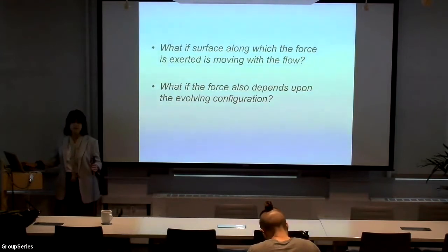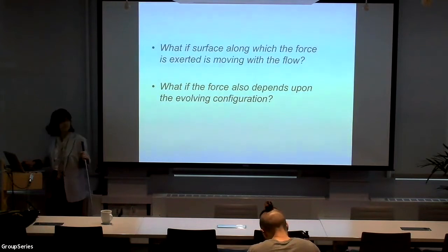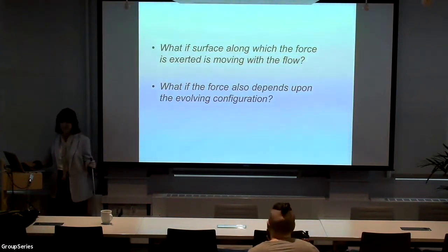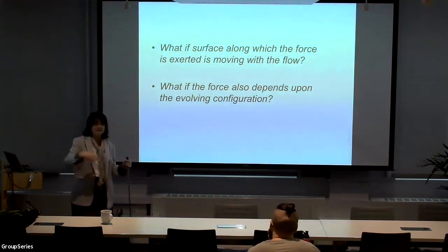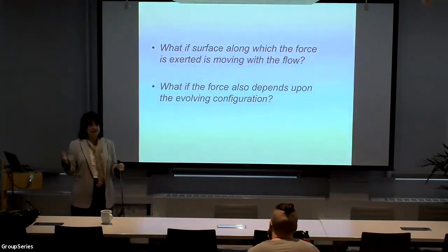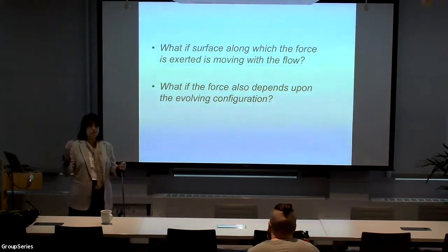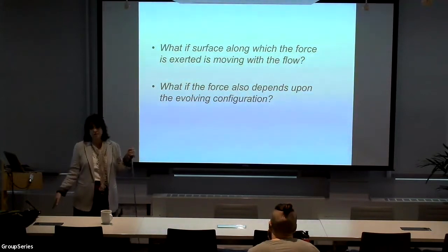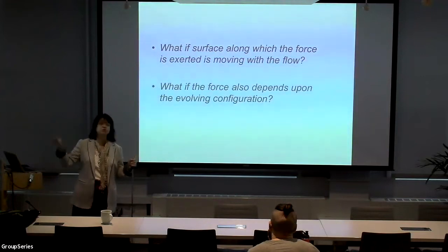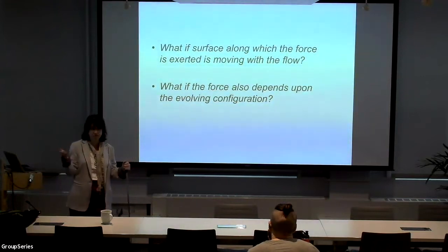But the fact is, many of you are stuck in Stokes flow, aren't you? That's the problem with Stokes flow. You're stuck in there, right? We've got reversibility. You change time by minus time, which has a lot of implications in terms of stroke forms. Nothing could swim at Stokes flow in a Newtonian fluid if you just paddle and then paddle back. You will just move forward, and then when you put your appendage back, if you go through the same sequence of motions, you'll end up where you started.